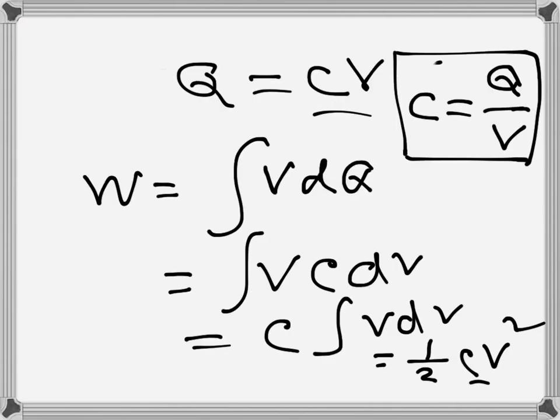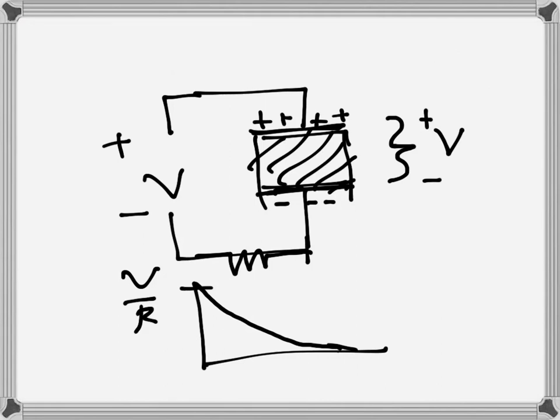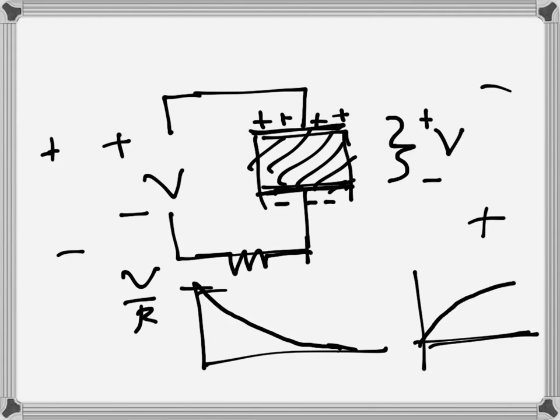So basically a capacitor is a dielectric material sandwiched between two electrically conducting plates, and it doesn't allow any DC current to flow. However, it allows AC current to flow, and that happens in this way: when there is an applied AC voltage, let's say with a certain frequency, the voltage keeps changing, the direction keeps changing, once this direction and once that direction, and the transient current is like that, and the capacitor voltage, which I didn't draw before, is like that.